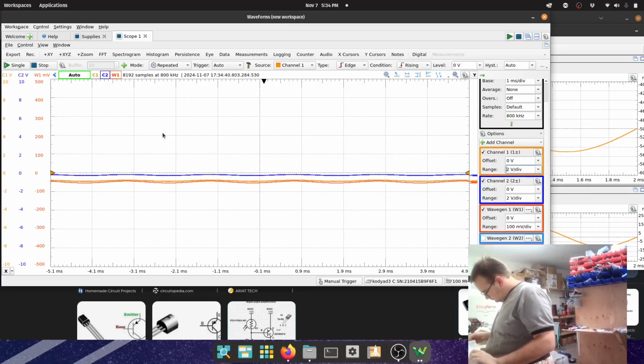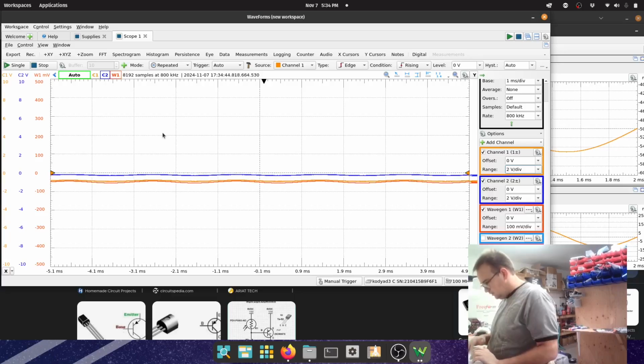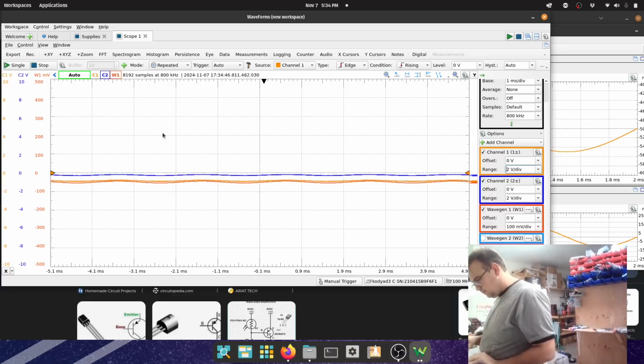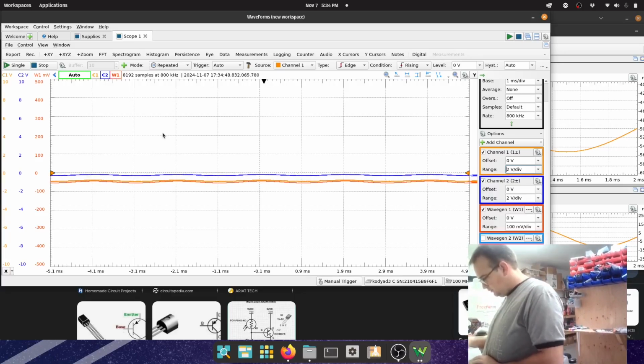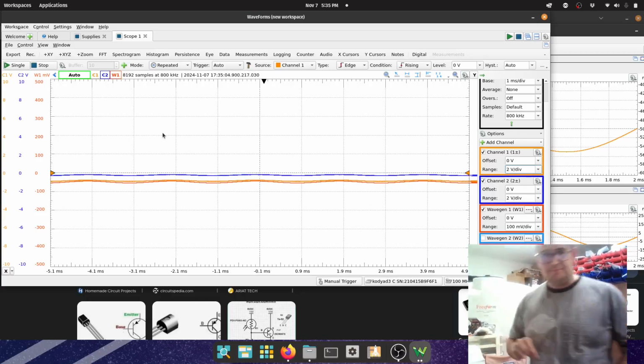So now we'll try this connection. It will force the amplifier to drive this input to the voltage applied at the other input, pin 5. As a consequence, we will trick the circuit into amplifying by about 11 times. Okay.